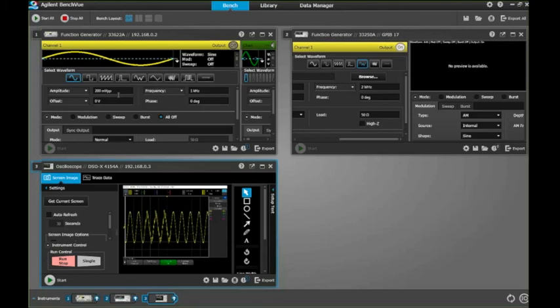But if you have a smaller waveform and you want to actually view the file, you can use the .arb file. One other thing I wanted to mention is that you can use .csv files as well with your Trueform generator. You can import those fairly easily via a USB stick or maybe just drag and drop. Import that, and the generator can output and interpret that CSV file into a signal.